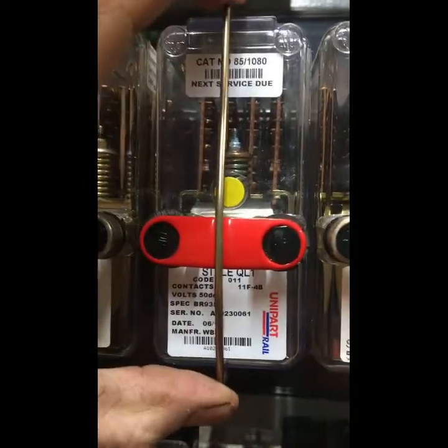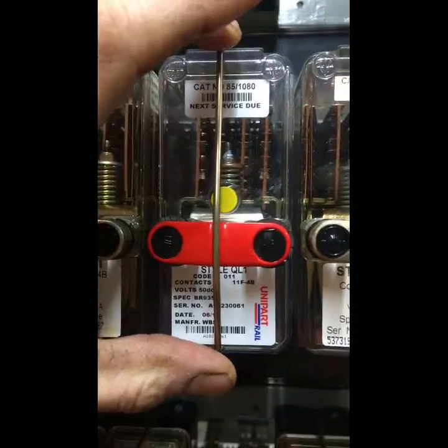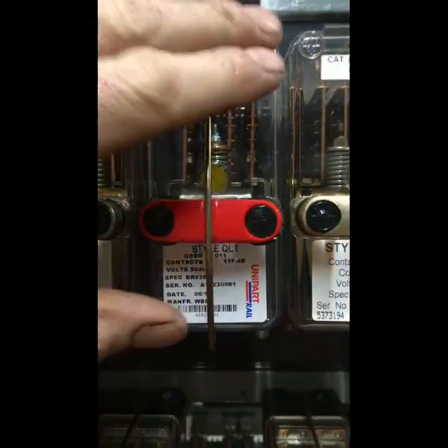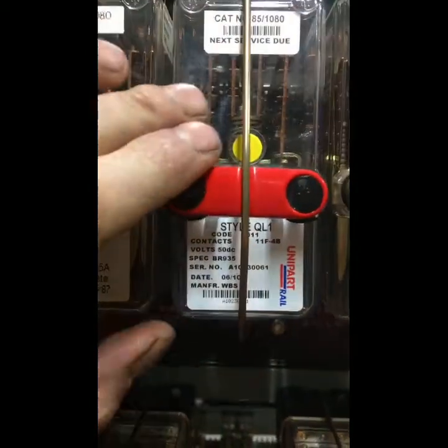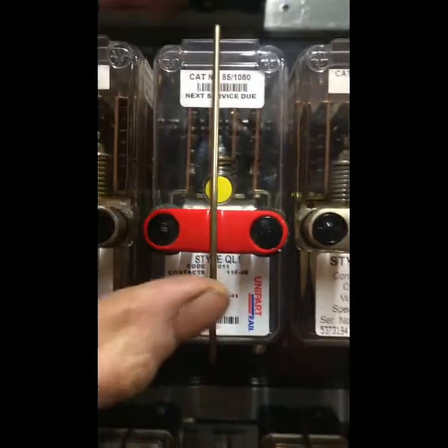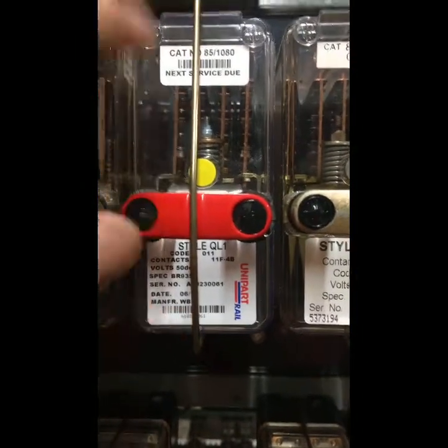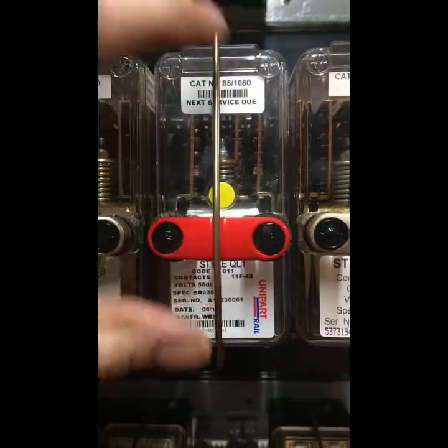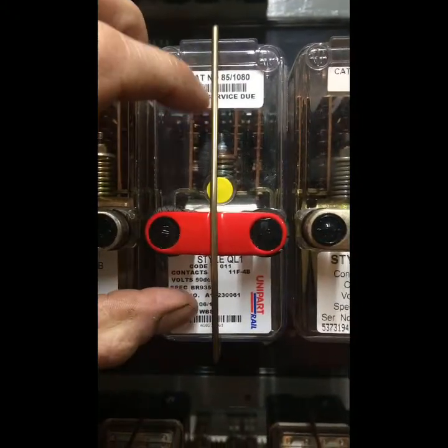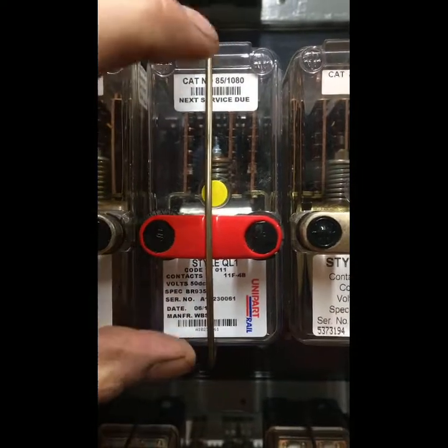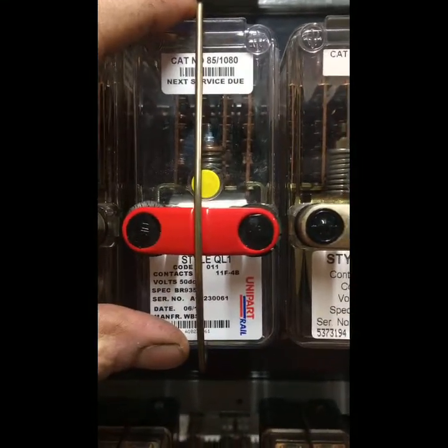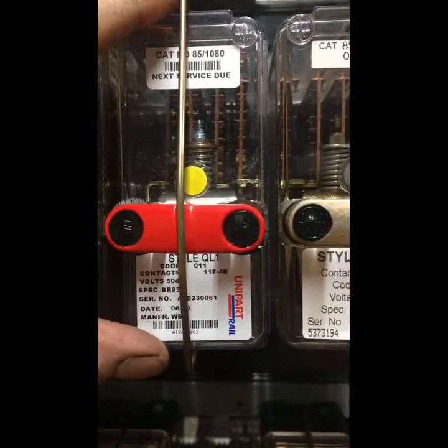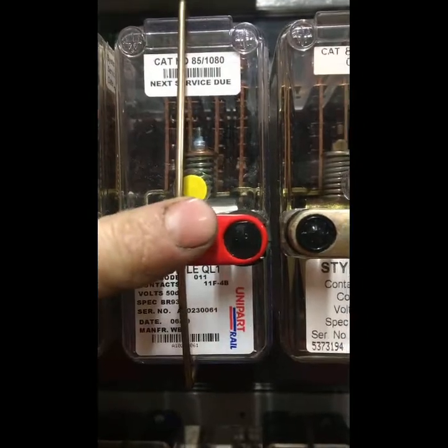When one of these relays fails, we have a test set that is used to put that relay into the correct position. So as part of the tests, the maintainer will look at this and go, this relay has failed, what position is it in? Is it up or down? And then the replacement relay will be in the same position. It used to be senior testers used to be able to strap the circuit to get that into the correct position. We as maintainers are not allowed to do that. We have a test set that puts that into that position. That's how we do that. You may be lucky that the relay you get out of the stores is in the correct position to start with. It just depends. But that's what this red band signifies.